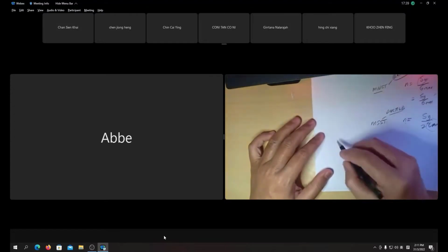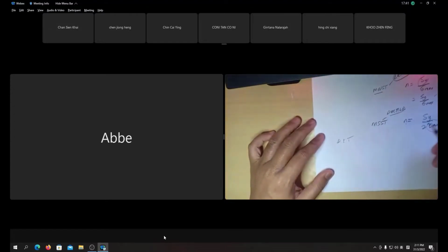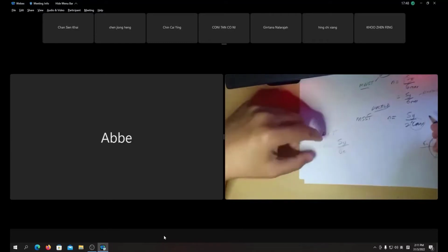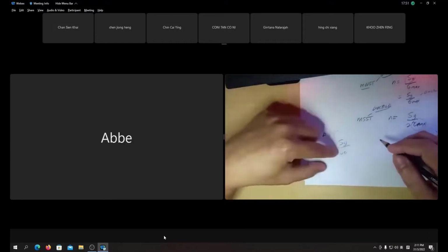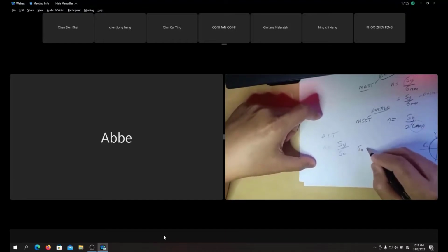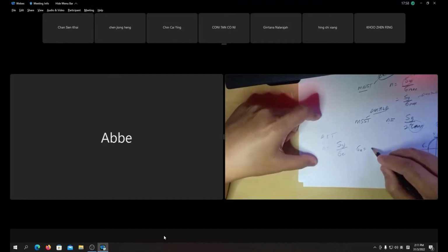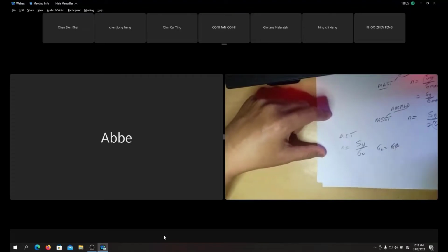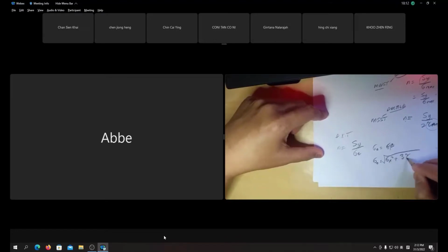But for DET, the safety factor is your SY over your sigma equivalent. Equivalent stress changes the shape but not the size. With distortion energy, there is sigma equivalent. What is the equation? I need to recall it. The shortcut is sigma equivalent equals the square root of sigma x squared plus 3 tau xy squared.